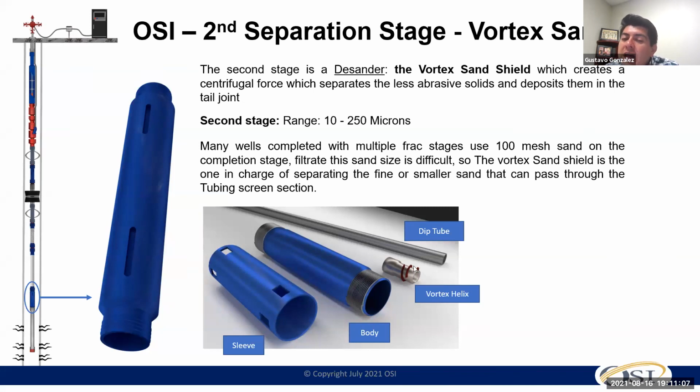And the way that you do that is based on the angle and the number of spirals that you have. That determination is translated into the amount of delta P that you're generating at this point. You're going to either increase or decrease the acceleration of the particles, being able to knock those particles through the wall and have a better separation. There is always a balance.